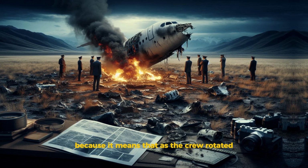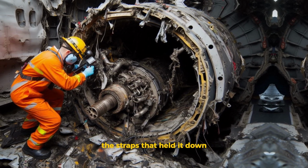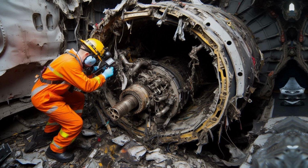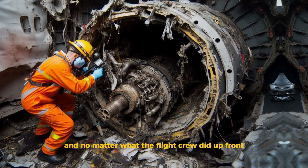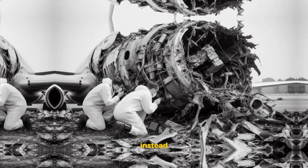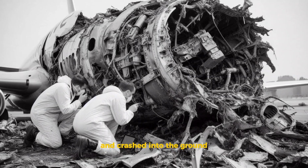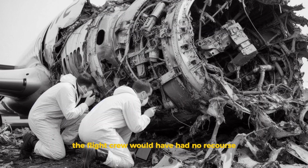it means that as the crew rotated, the insufficient strapping of at least one of these vehicles would have simply ripped through the straps that held it down, causing all of the damage that we just discussed, effectively disabling the aircraft's pitch control. So the aircraft would have continued to pitch, and no matter what the flight crew did up front, or how hard they pushed the yoke forward, nothing would have changed. Instead, the aircraft would maintain its nose-up attitude until it ran out of momentum, entered an aerodynamic stall, and crashed into the ground. Once the horizontal stabilizer had been damaged, the flight crew would have had no recourse.